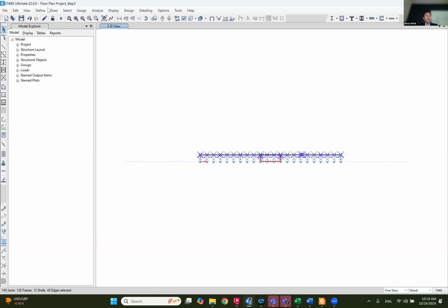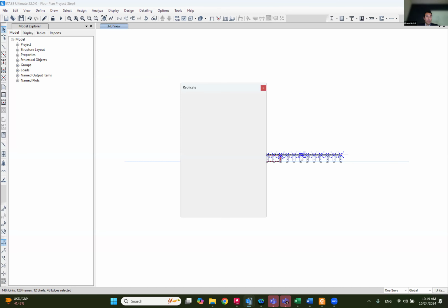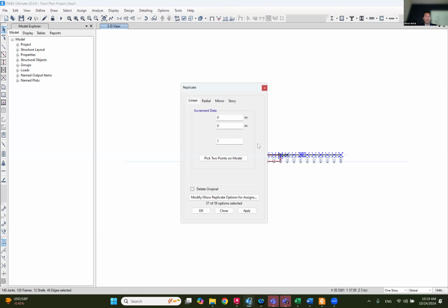So I selected all this, and what I'm going to do, I'm going to go to edit, replicate, and I'm going to replicate this story in the next nine stories. Like I will go to replicate, and then I hit story, and replicate this story in story number 2 up to story number 10.